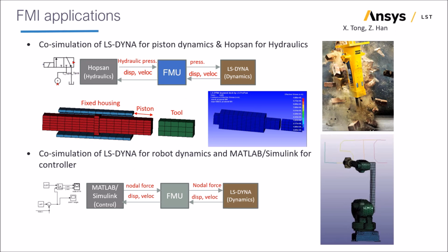Here are a couple of examples. You will see the term FMU on these slides. This stands for Functional Mockup Unit, which is a set of communication instructions specific to a particular model, which is formatted in accordance with the FMI standard. In the upper example, LS-DYNA is interacting with a specialist hydraulics code to model a pneumatic drill. The hydraulic model sends pressure to LS-DYNA, which does the dynamic finite element calculation and sends displacements and velocities back